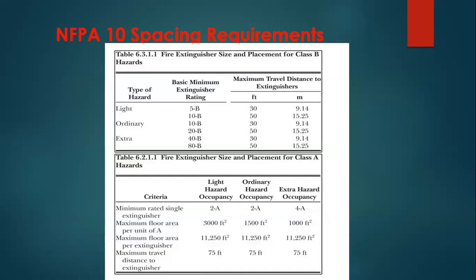If the turbine enclosure is giving off any type of flame or any alarms, of course the accommodation will be active because of the fire alarms. When they try to fight the fire, they cannot remove the extinguisher available in the accommodation and take it to the turbine enclosure. The extinguisher in the accommodation is meant for that area only. Let's say they take a carbon dioxide extinguisher down into the turbine enclosure where the metal is on fire and apply carbon dioxide there. What will happen? It will propagate the flame, right? That is why the extinguisher that is available in an area should be used for that specific zone.